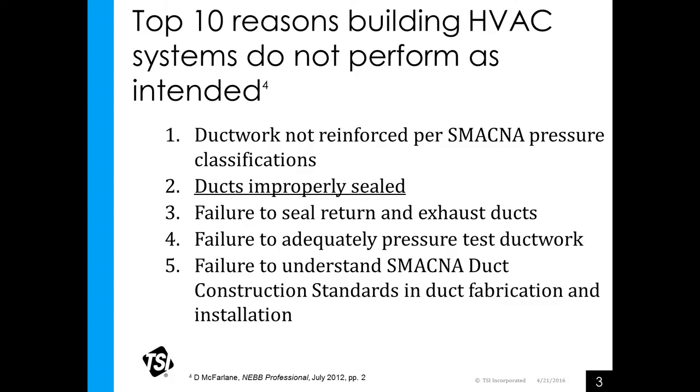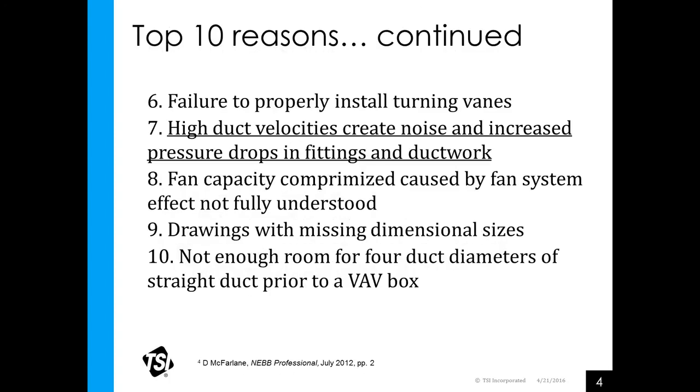And just as important, we talked about sealing, failure to seal the return ducts. I mean, this proves duct sealing is effective if you do pressure test the system. In residential applications, the easy way to determine duct loss is to have the HVAC system off and all your exhaust fans on. It's a little more complicated in commercial applications, so duct sealing is quite important.